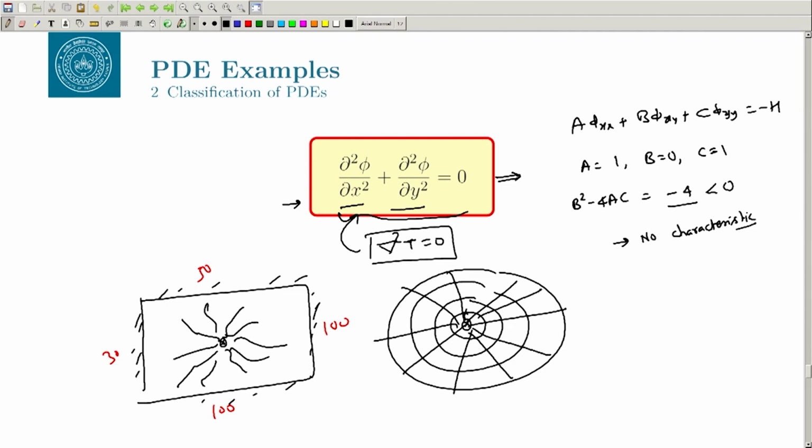Okay. So, there are two terms, one is the domain of disturbance and domain of influence. So, here we have disturbed it here only maybe here, but because this is an elliptic problem, the domain of influence is everywhere. Okay. So, the value at this particular point depends on the value of every single point in the domain, okay, everywhere in the domain.